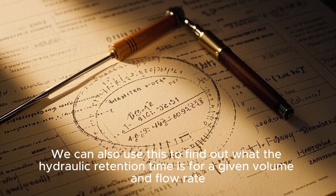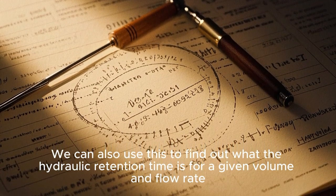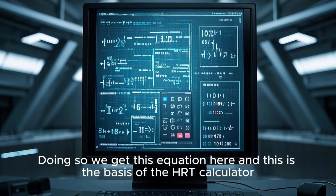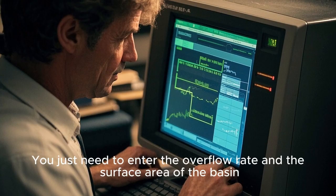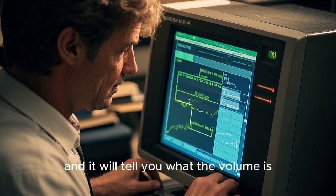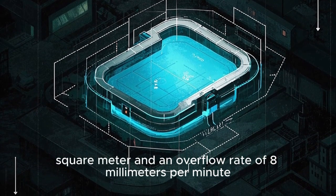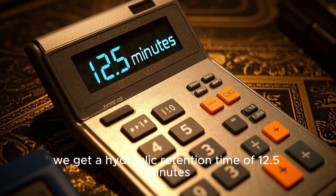Now we know the diameter of the pipe that would give us an overflow rate of 8 millimeters per minute. We can also use this to find out what the hydraulic retention time is for a given volume and flow rate. To do so, we need to rearrange the overflow rate equation and solve for the volume. Doing so, we get this equation here, and this is the basis of the HRT calculator. You just need to enter the overflow rate and the surface area of the basin, and it will tell you what the volume is. Let's say we have a basin with an area of 1 square meter and an overflow rate of 8 millimeters per minute. If we plug those values into the calculator, we get a hydraulic retention time of 12.5 minutes.